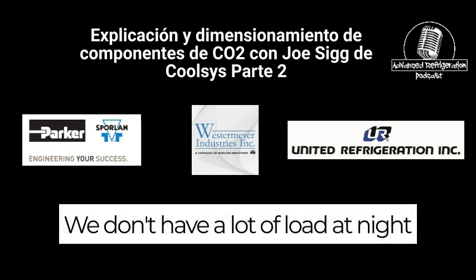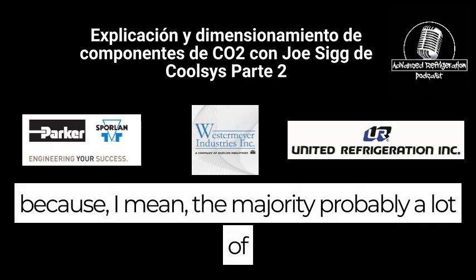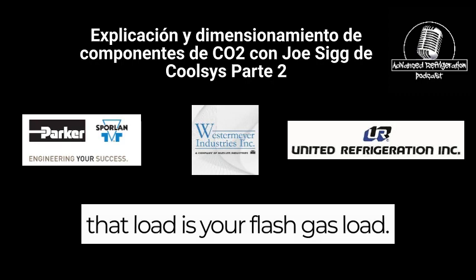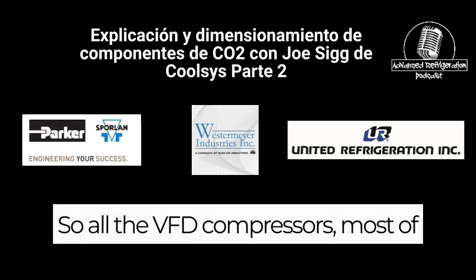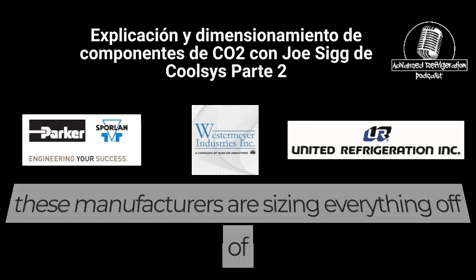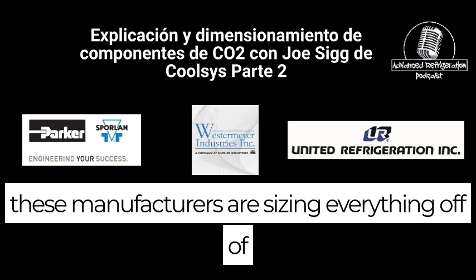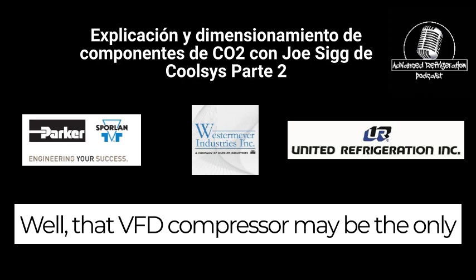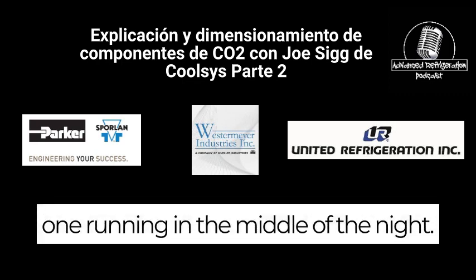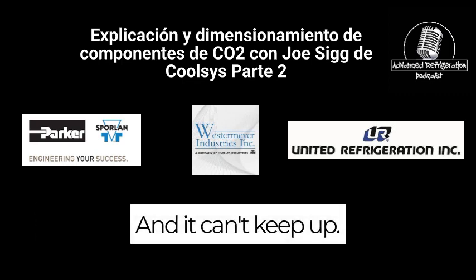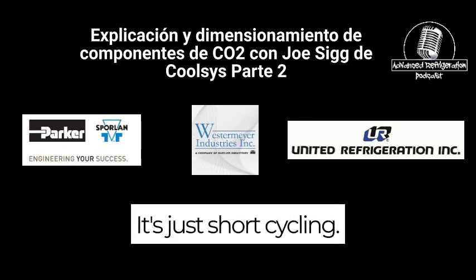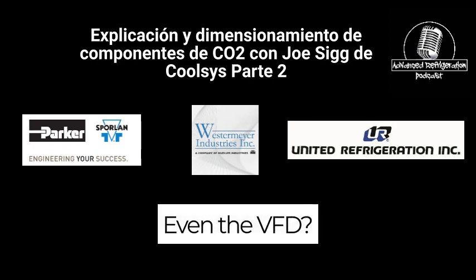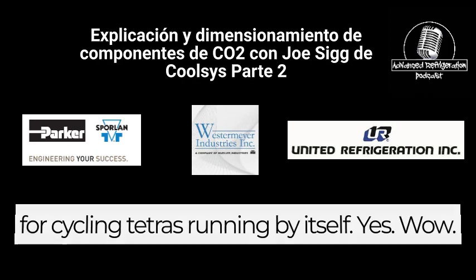We don't have a lot of load at night, because the majority of that load is your flash gas load. So all the VFD compressors, most of these manufacturers are sizing everything off of that peak flash tank load. Well, that VFD compressor may be the only one running in the middle of the night, and it can't keep up. It's just short cycling. Even the VFD is causing short cycling, just running by itself? Yep. Wow, that's pretty amazing.